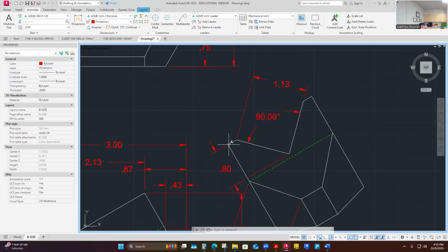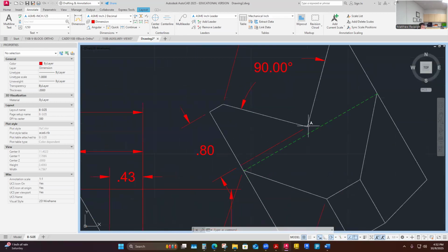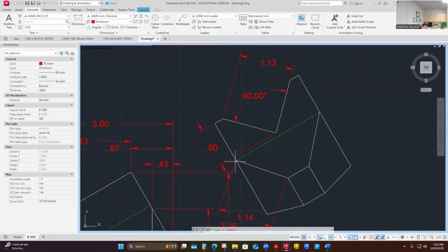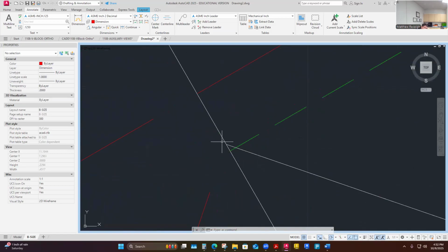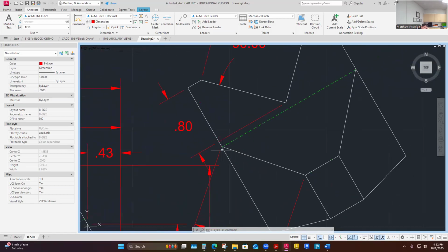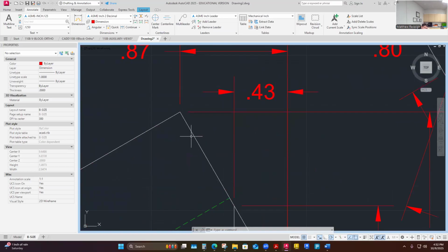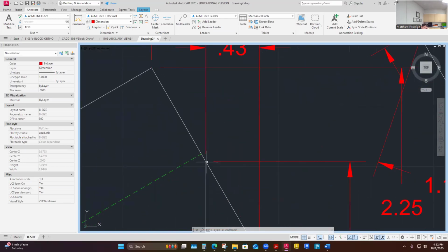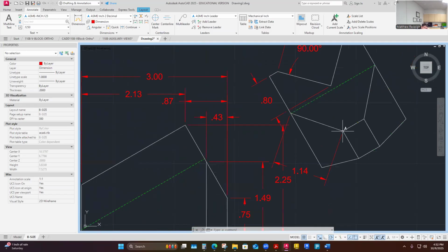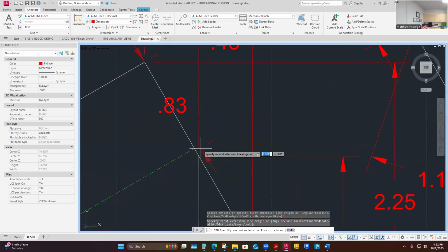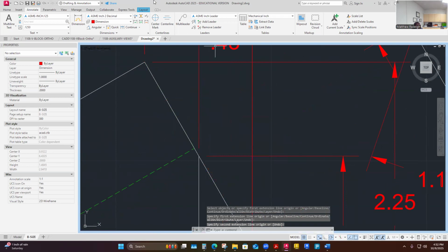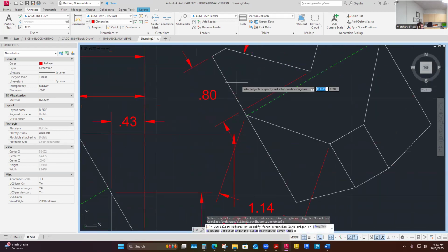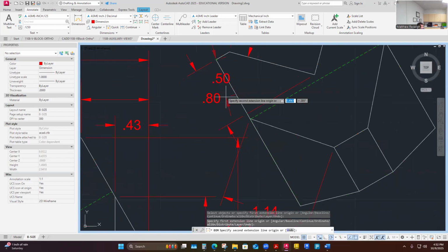And then 0.2 over, and then I go down, and I'm really looking beyond that. And I'm like, well, what's this length here? There's a lot going on at this corner here. I want to decide what's true length and what's not. Well, technically, this is true length in the front view down to that point. And I have it in the auxiliary view as well. So I'm going to snap that dimension, I think. I could snap it here, but it would be an aligned dimension. And maybe I'm going to restrict those to just my auxiliary view, being my little messier view here with aligned dimensions.